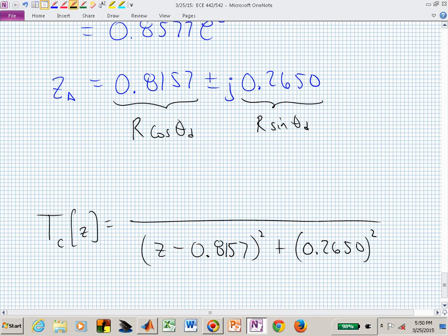We didn't say anything about the numerator, but let's go ahead and assume we have a one-step delay between when we excite this system and when we start to get a response out. And that would correspond to an actual time, 10 milliseconds. That means that we're putting a 0 right at the origin.